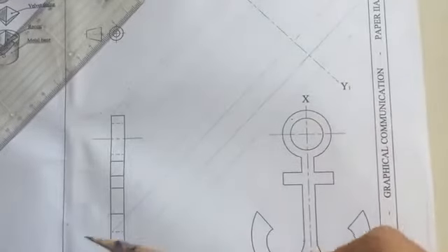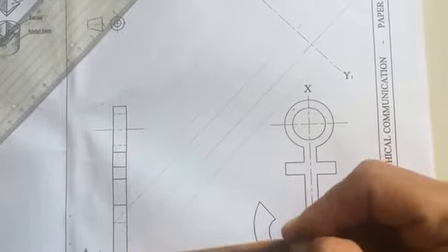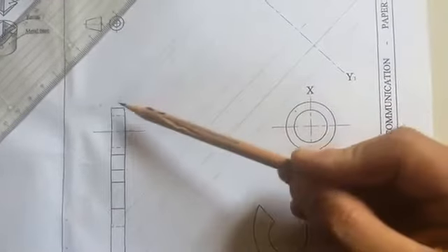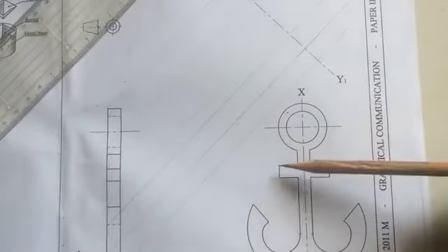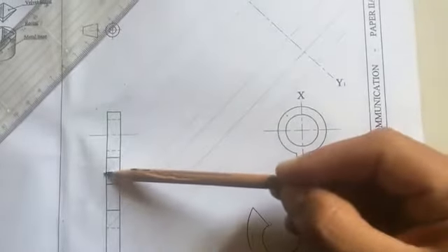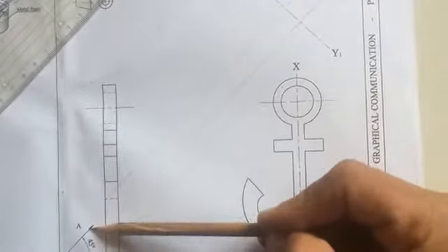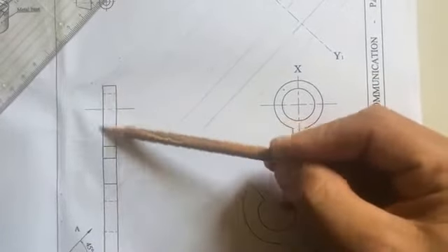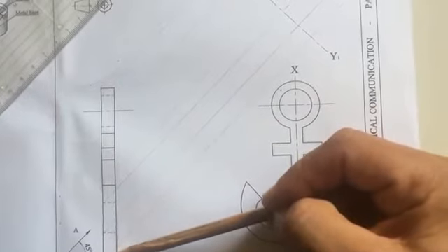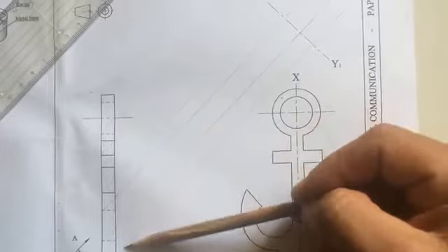Now what I've done so far is I've already projected from the front face. Projection lines from each detail, from each point I have. So if you've got this corner, I've projected a 45-degree line onto the XY line. I've taken the front face because the arrow is looking at the front face. So I've projected the front face first. That's the most visible point. Don't project from the back because most of the back is going to be hidden.